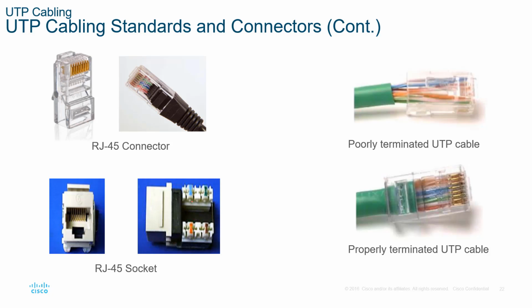So how do we know if we're making the cable correctly? A properly terminated cable will look like this. The important part is this center part here. We have this plastic punch down actually punching down onto the cable. Thus, if we're pulling the cable, that provides a certain level of protection. Here, we don't have that protection, so if we pull on the cable, we're actually pulling on the plastic core portions and thus can be damaged.